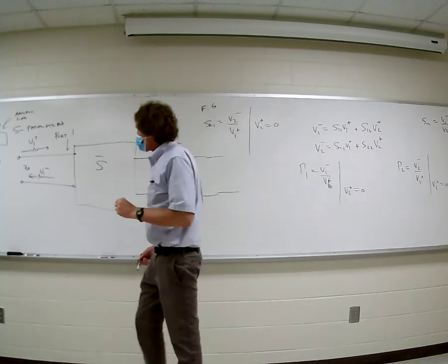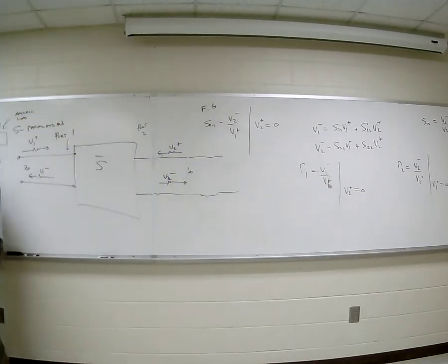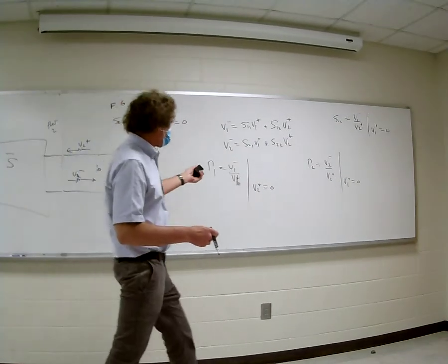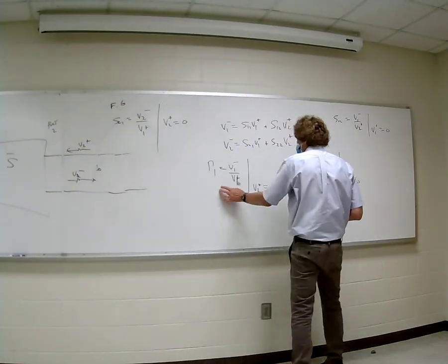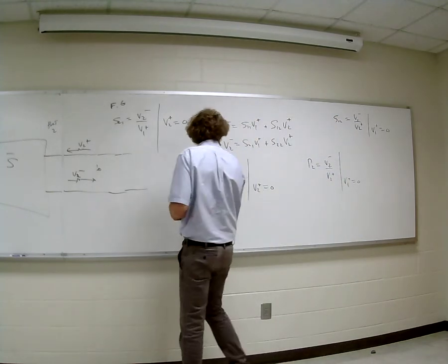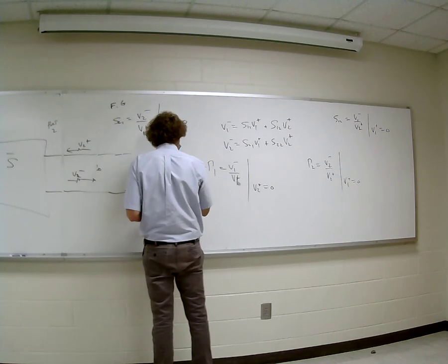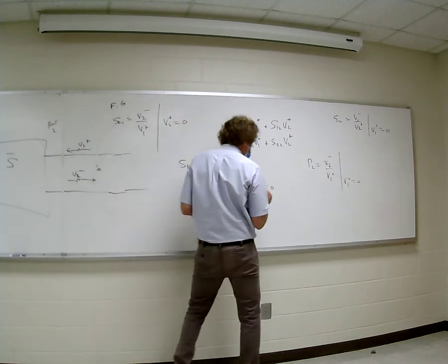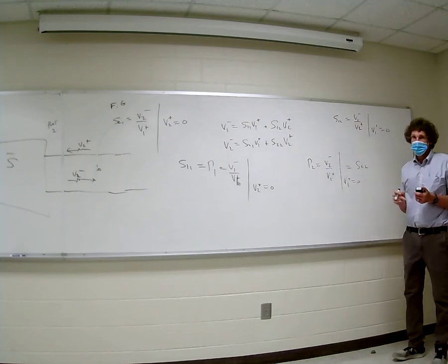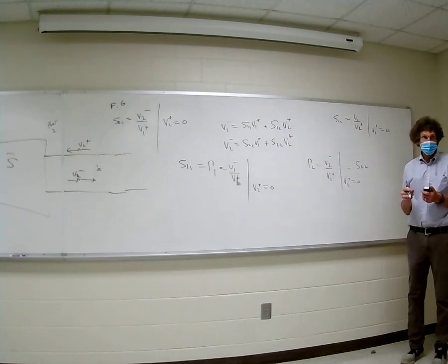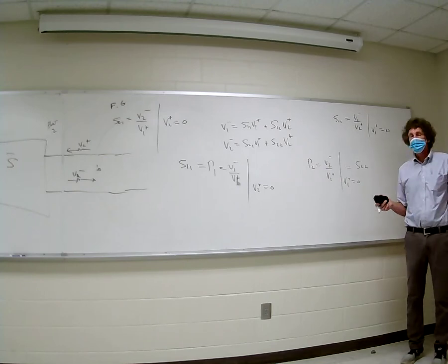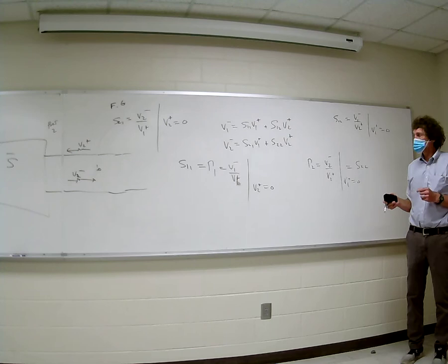So let's go ahead and get the S parameters of this. I'm going to do it over here. When I take a look at this, the first thing I usually go for is a reflection coefficient right here for port 1. That would be equal to simply, I didn't put this down, that's S11. I'm sorry I did. This is S22, isn't it? By definition. Right, so when we talk about reflection coefficient on port 1, it's S11. Reflection coefficient on port 2 is S22.